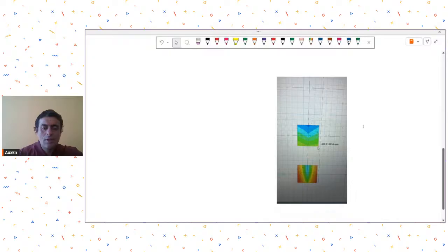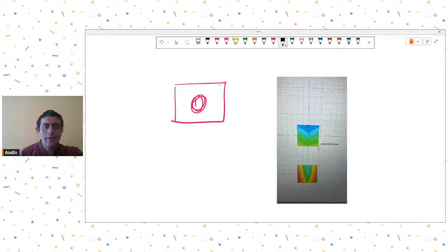Question mark. So see, what happens in SAFE is that when you have a single pile cap, and let's say this is your pile, and then there is one column above. This black box is the column above, and this was your pile, and this is your pile cap. So what happens usually is that we only assign stiffness to the pile, isn't it? In SAFE, we model the pile using a spring, and then you have modeled a shell. So this is your shell element, and then there is a column on it.